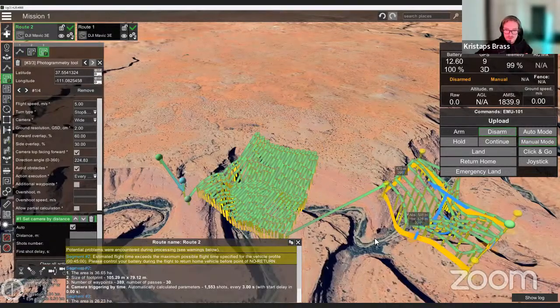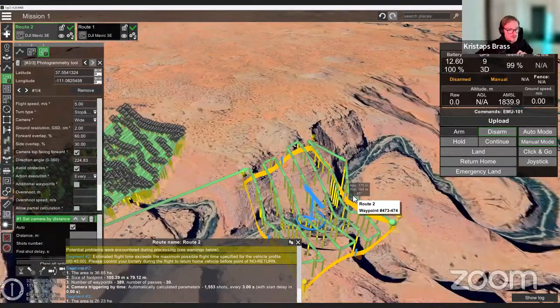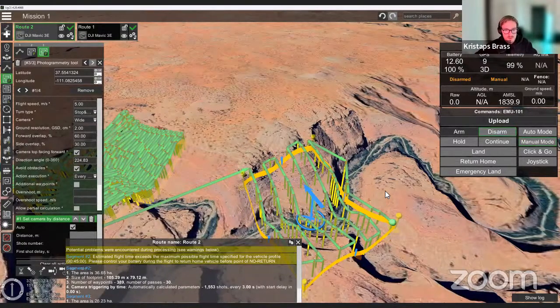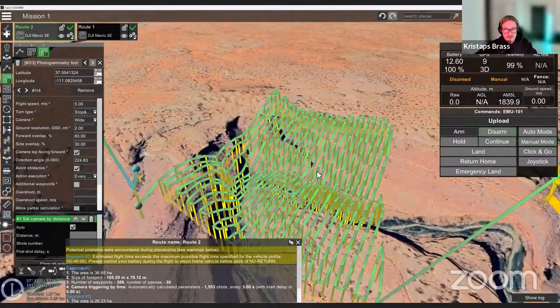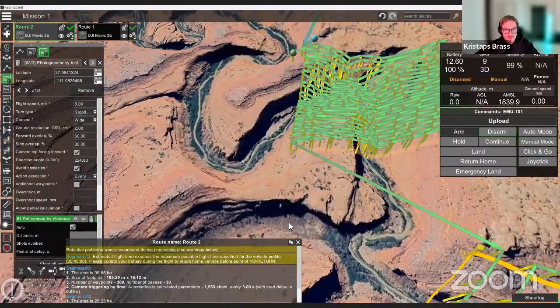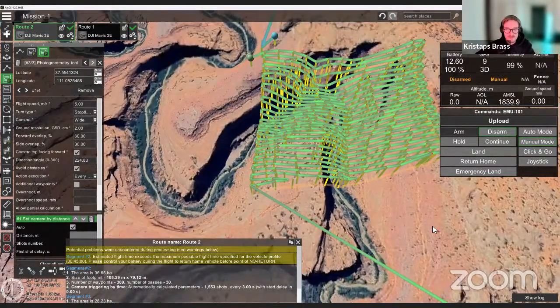One other thing I want to show you, and I will probably also get to this a bit later: if you want to create digital twins using drones, which is popular now, then there are a few additional things you might want to do. So let's say in this case, we have this photogrammetry mission with 80-80 overlap, and then we might want to do not only those nadir images, but also images at 45 degrees. So how do you capture those types of images from different angles?